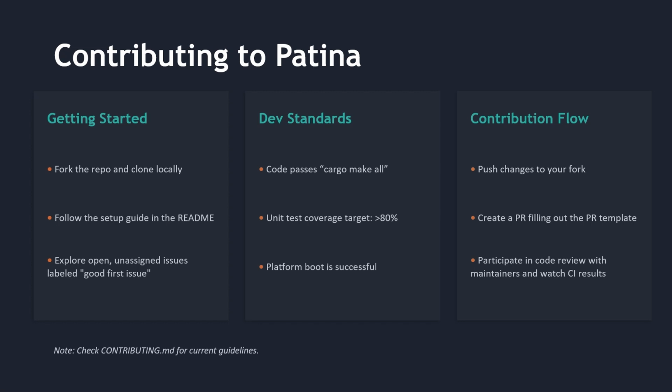Finally, everyone needs to make sure that the firmware code that they contribute can boot on a platform. In Patina, we do that using the virtual QEMU platform since that's publicly available and easy to hook into CI. Whenever you create a pull request in a Patina repository, we have a workflow that will take your changes in the Patina code and follow the process that I mentioned earlier, going from Patina DXE Core QEMU to using the Patina code to Patina QEMU using that resulting EFI binary.